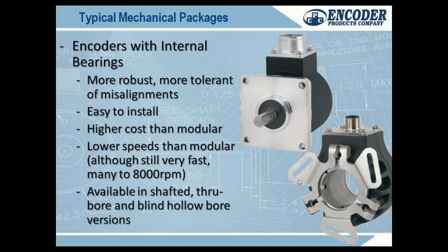The encoders can tolerate quite a bit of shock and vibration, and on most quality manufacturers will admit to their values and put it on the data sheet. It's on our data sheet and our competitors who make quality products, so that you know what it'll tolerate for shock and vibe. They can take a lot. So again, if you're vibrating the whole machine, I recommend this. And if you have a vibration or run out on a shaft, you'll want to put a shafted encoder on there.